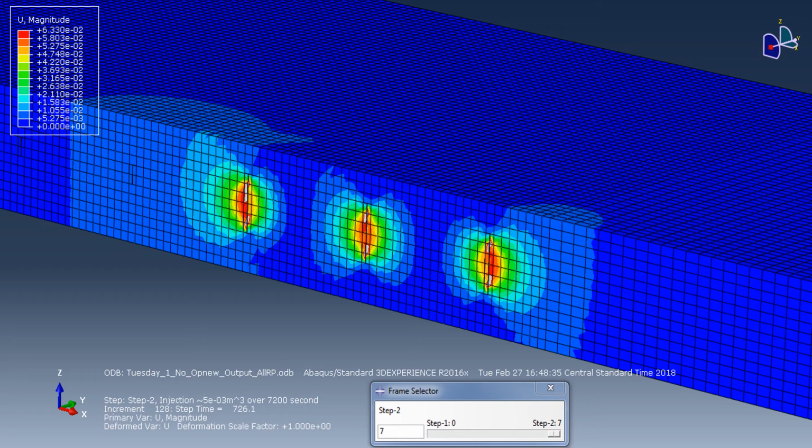Results of the simulation can be used to determine changes such as stress reorientation and fracture initiation and propagation. By importing the fracture geometry created in our simulation into a reservoir simulator, pressure transient analysis can be used to determine fracture conductivity and possible refracturing. Parametric studies will be done to see how injection rate, pump time, viscosity of fracturing fluid, and cluster spacing affect fracture propagation.